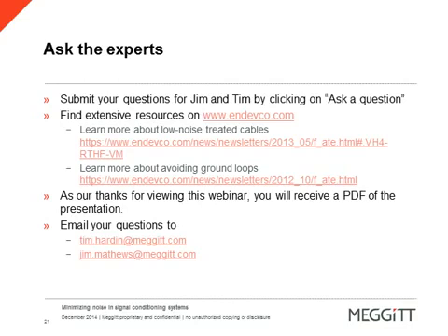Also, you might want to look at, even if it's not low noise treated cable, a twisted pair or a shielded twisted pair, even for low impedance outputs, because that cancels out that magnetically coupled noise. The high frequency stuff depends on what it is and what the source is, and how it can be addressed.